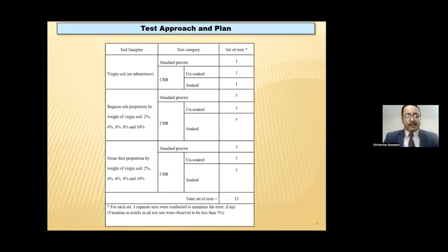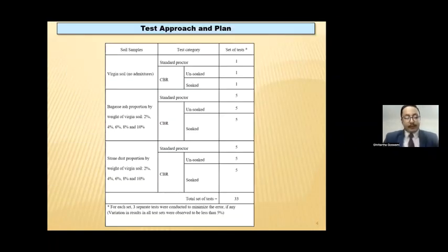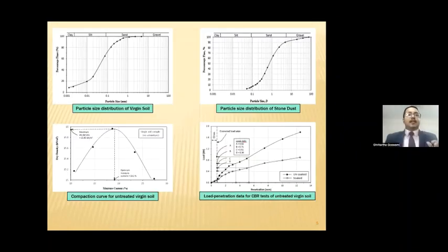Previous studies also suggested that bagasse needs to be treated with lime or cement as an activator, especially when the soil is expansive or very soft compressible clay. But in this study, the virgin soil is silty clay, so there is no need for an activator, which might enhance the cost significantly compared to the relative benefits in the enhancement of the compaction and penetration characteristics. So considering the local soil characteristics, the activator has not been used in the soil stabilization.